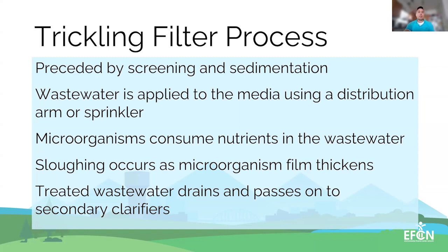One quick note, trickling filters can be a misleading term because we tend to think that means that solids are being strained out from the wastewater, but in actuality, what is happening is the organic matter in wastewater is being absorbed by the microorganisms in our fixed film.